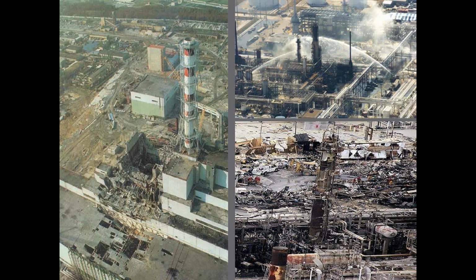Many of you on the call, I don't know how old you are, but the lower right-hand corner is Bhopal, India. Again, a reactor where a temperature switch, the first redundancy, failed, a pressure switch, the second redundancy, failed, a pressure relief valve, the third redundancy, failed. And when this tower blew up, it killed around 20,000 people, including operators and all the people in the village next door to the plant. Highly toxic chemical. So again, 3 redundant systems that weren't being checked, PMs weren't being done on them, and lots of people lost their lives that day.